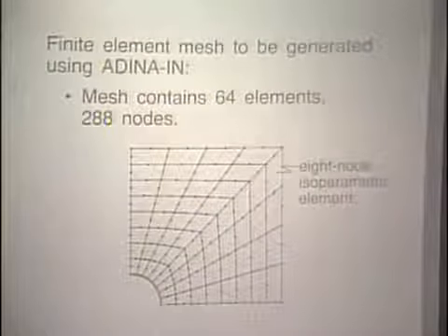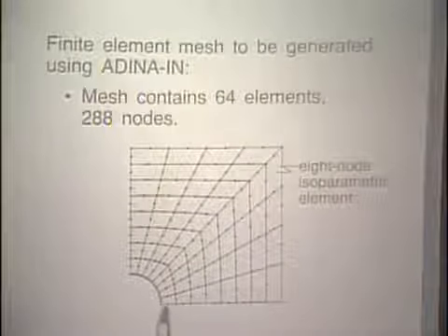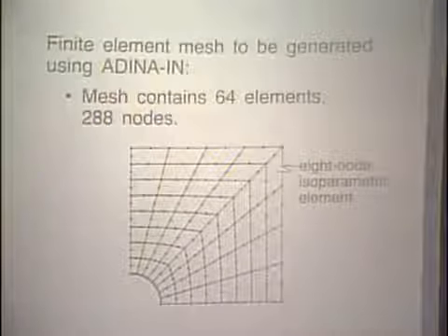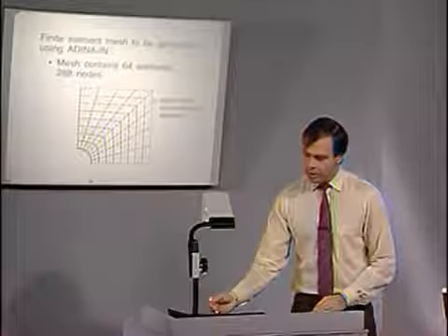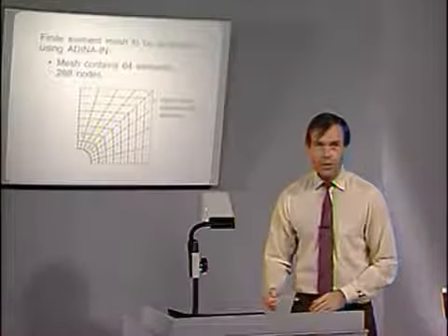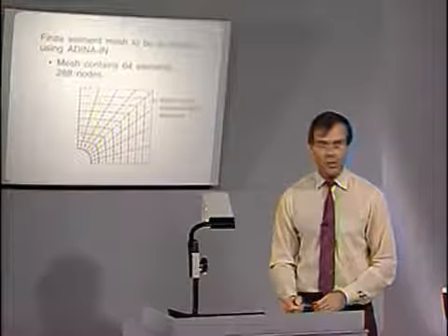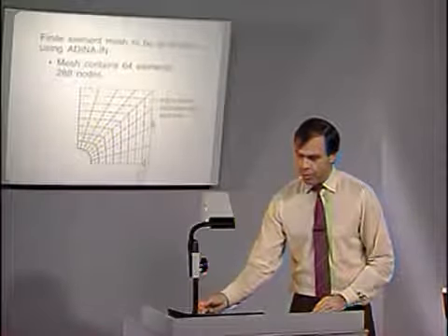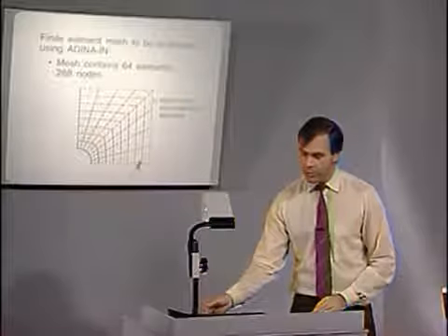that, as I said already, indicates clearly once again that we have used the wrong boundary conditions down here. So we go and correct the boundary conditions down here and rerun the analysis. In other words, call ADINA again, and those results that we obtained then once again are plotted, displacements in other words are plotted by plotting the deformed mesh onto the original mesh.